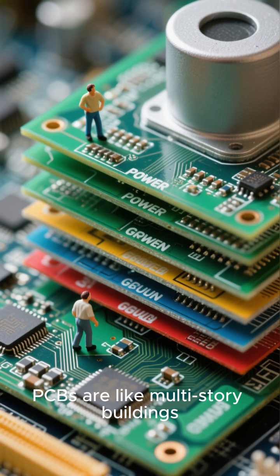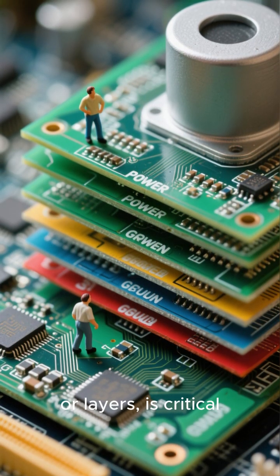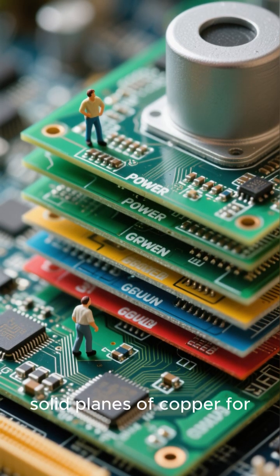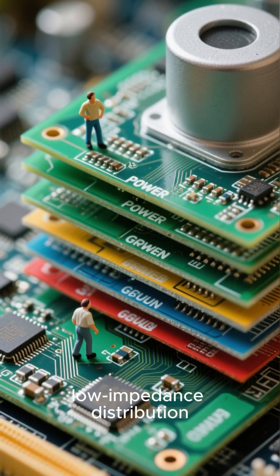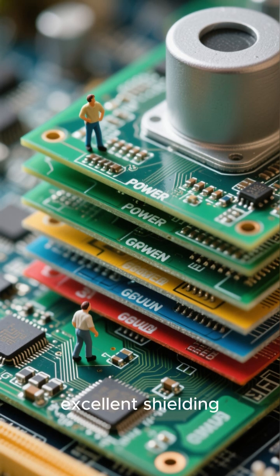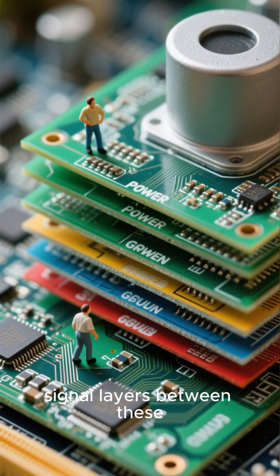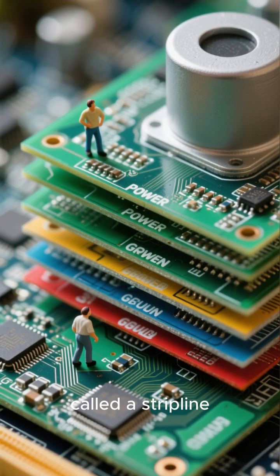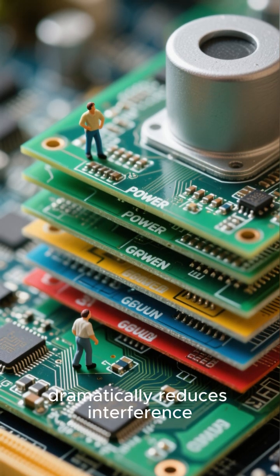Modern PCBs are like multi-story buildings, and how you organize the floors or layers is critical. A great strategy is to dedicate entire layers to be solid planes of copper for power and ground. This creates a low impedance distribution network that provides stable power to all your components and excellent shielding. You can then sandwich your high-speed signal layers between these ground or power planes. This configuration, called a stripline, helps contain electromagnetic fields and dramatically reduces interference.